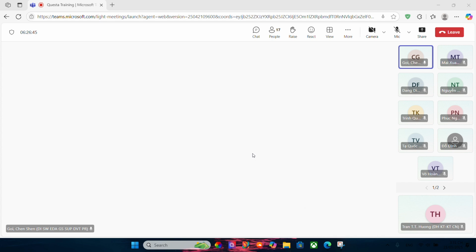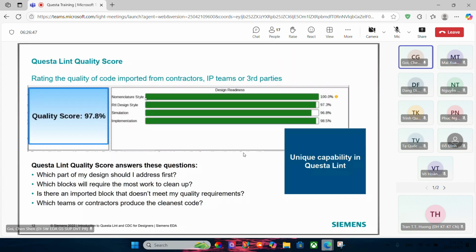a check that ensures all input signals, such as those with the underscore i suffix, follow the naming or nomenclature style. So this is categorized as what is also known as naming style. And RTL design style check is basically just your code structural check.